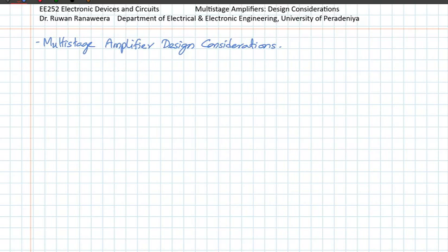But to achieve high gain, as mentioned before, we need common emitter amplifiers so that you can have higher voltage gain. In the second or third stage, or if you have multiple stages, you can have several common emitter amplifier stages to achieve the high voltage gain. Now you need to remember that you cannot arbitrarily increase the gain.